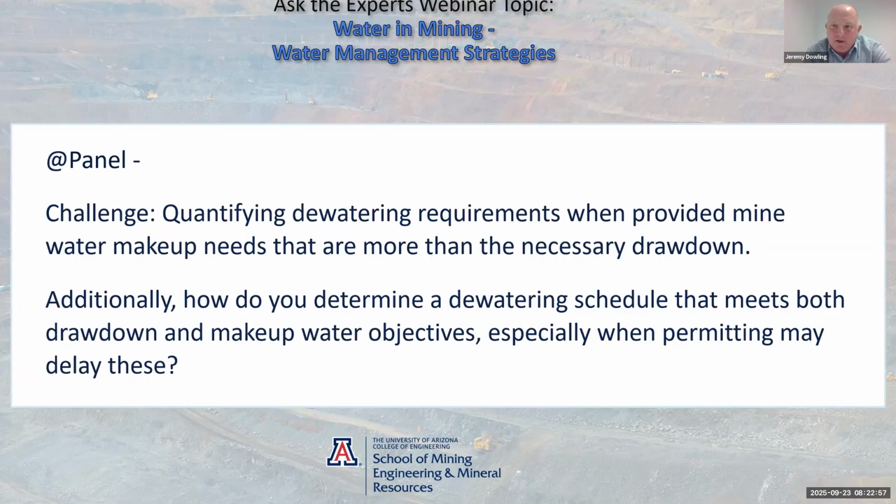And so what we did is we tried to be very strategic and targeted with the dewatering wells in the pit. So in trying to dewater the pit on a wide scale basis for long-term purposes, we concentrated the pumping wells into the areas of the short-term mine plan, and just created local drawdown that would enable short-term mining, and kind of moved the wells around and had a pumping strategy that still worked with a less than ideal pumping rate. So there's a few things you can think about there.